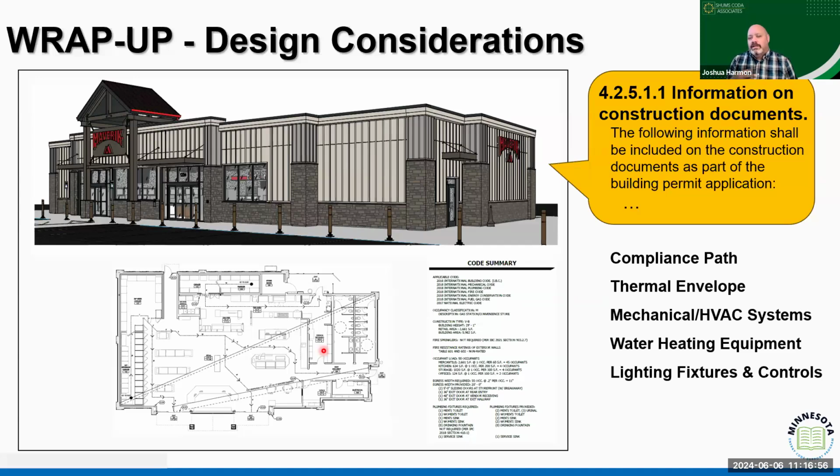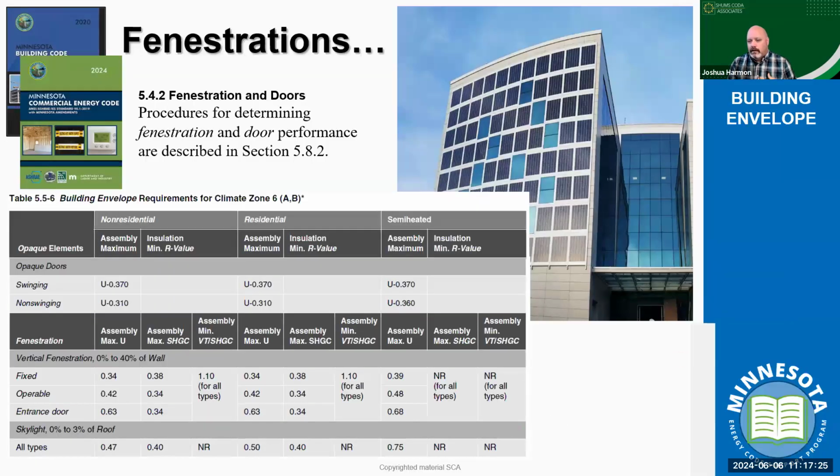And when we think about different occupancy type controls, I just got done teaching a class on occupancy controls and different lighting considerations. Again, if you're thinking about it in the context of top lit or side lit, daylight zones, that can really have an impact. If we're going to have a building that operates in an area with a lot of open windows, right? If we're thinking about this kind of a building, and we've got a lot of windows, we've got a lot of light coming in.